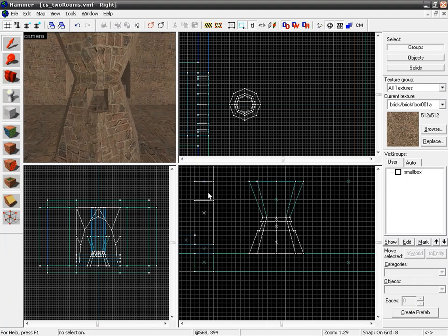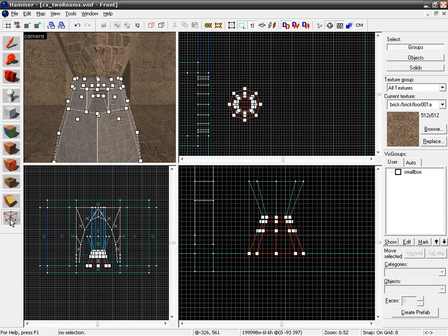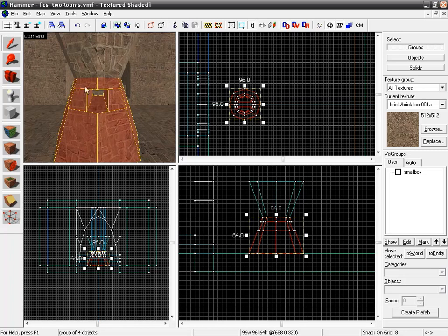Now, go back to the selection tool and click on the object we've carved. And notice how it's carved it into several new pieces. Carving can get quite complex, and for that reason should be used fairly sparingly. It is also a good idea to use the vertex manipulation tool to simplify edges on certain objects you've carved. This shape's been cut into relatively simple pieces, so I think we're okay to leave it for now.